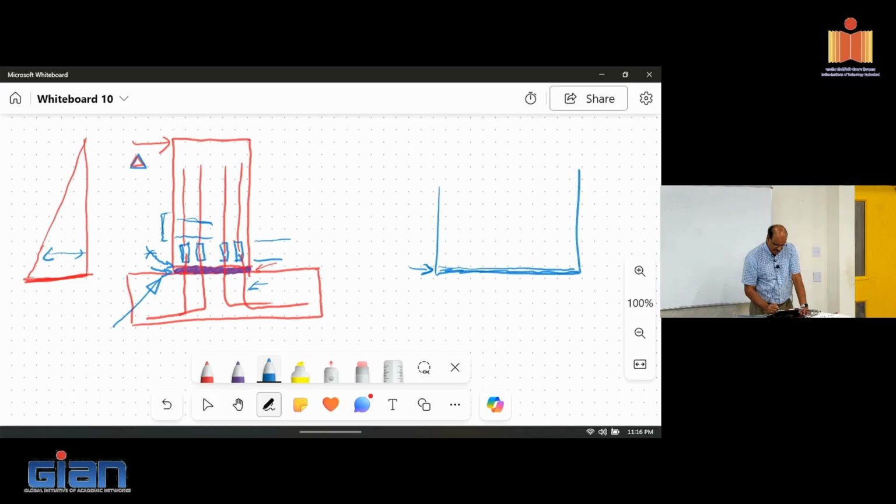But as I mentioned last time, because you are concentrating the displacement here, your strain at this location will be pretty high because you have a very narrow band where a large gap is opening up. So your strain hardening will take place a lot more at the interface, and therefore your penetration effect will also be relatively higher between the two.